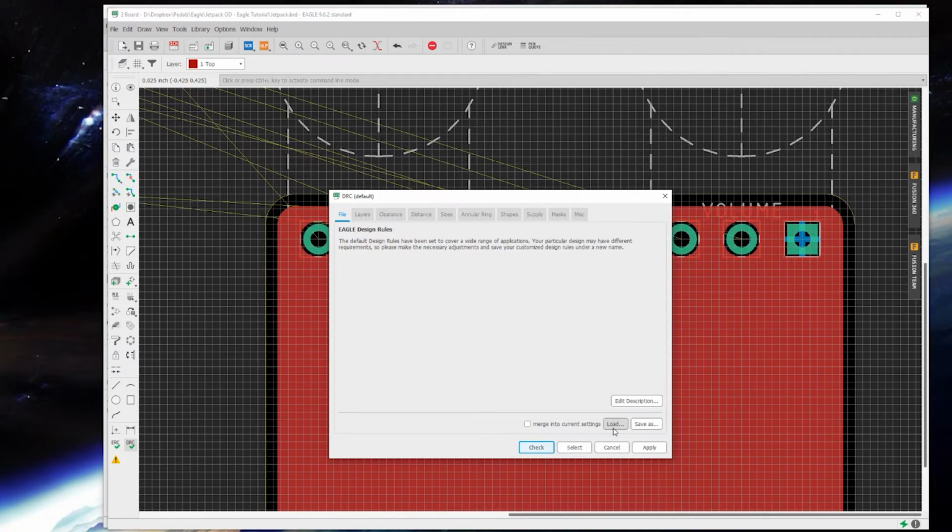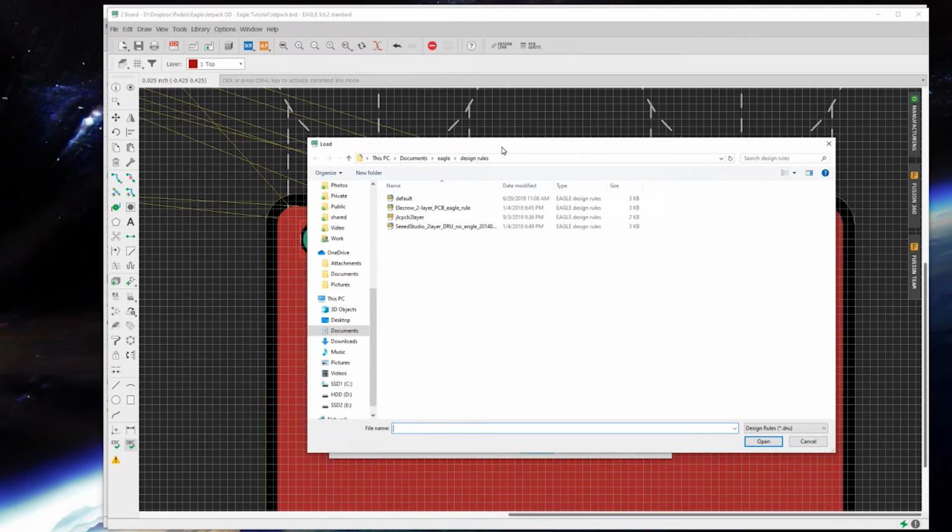And it's best at this point, I think, to go ahead and run this so that you know how much gap between the edge of the board and the edge of the copper that your fabrication house is going to use. For this, I'm probably going to get it manufactured by Elecrow, so I'm going to use their DRC file, and I'll link that in the description.